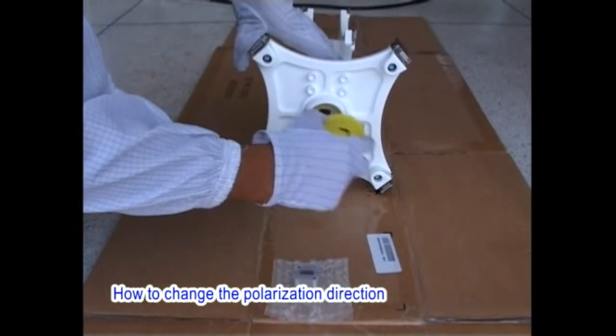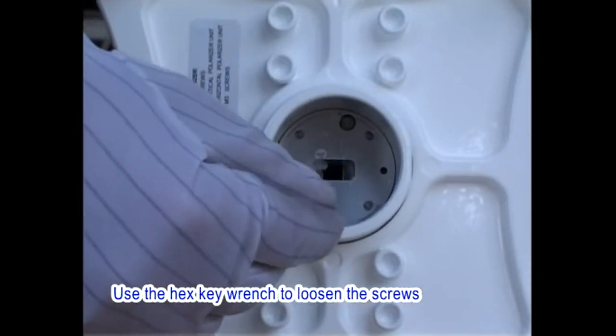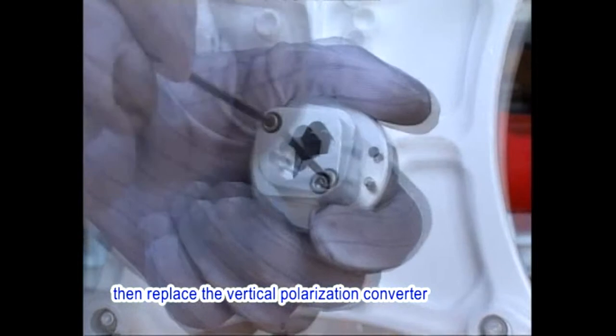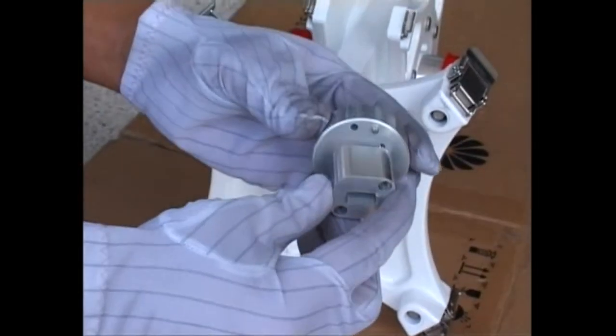How to change the polarization direction of the hybrid coupler? Use the hex key wrench to loosen the screws that fasten the polarization part in the antenna interface of the hybrid coupler and remove the polarization part. Then replace the vertical polarization converter with the horizontal polarizer.